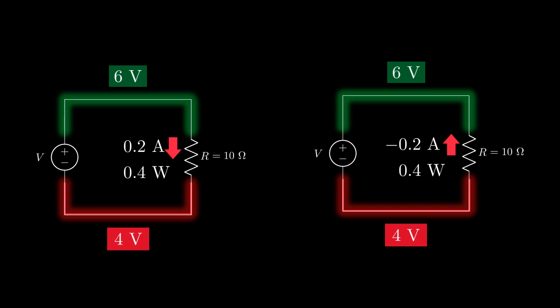That's the power of passive sign convention. Even though we almost made a mistake thinking the current is going in the upwards direction, it gives us the correct result either way. That's why you should always follow this convention. In fact, this example also emphasizes why you should consider negative currents. In my opinion, treat all numbers as equals. Negative numbers are also just numbers.